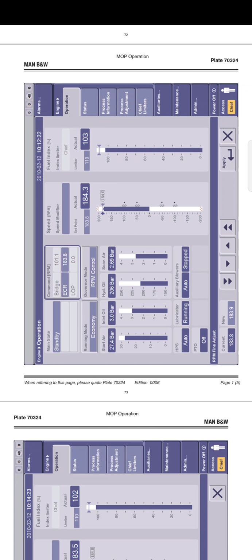That is, if the speed command set point is 183.8 RPM, it can be finely adjusted to 184. Moving the handle will disable the fine adjustment mode. The maximum fine adjustable speed can be adjusted within a predefined number of RPM. Note, RPM fine adjustment can only be performed in ECR command mode.